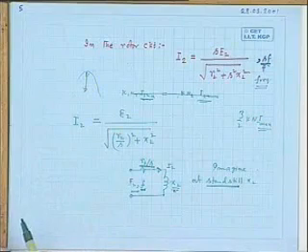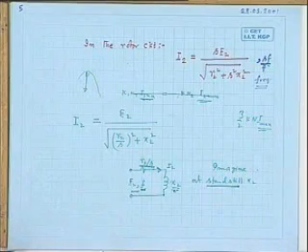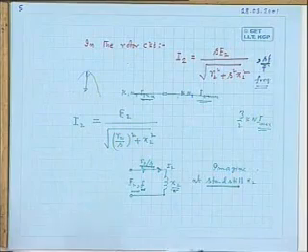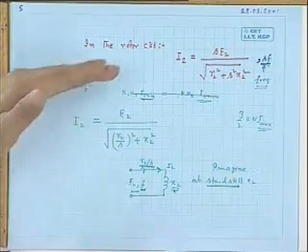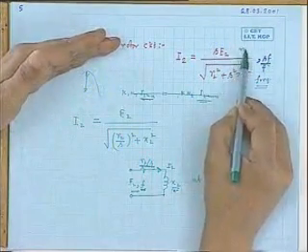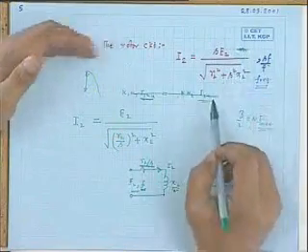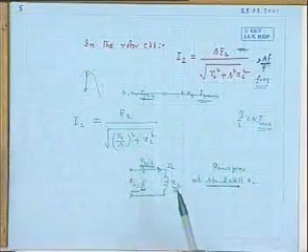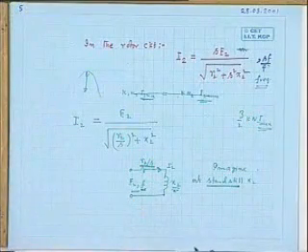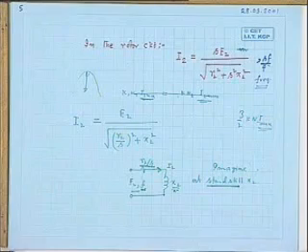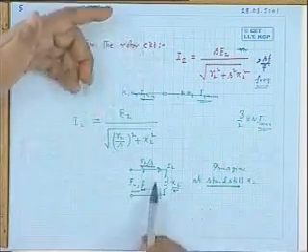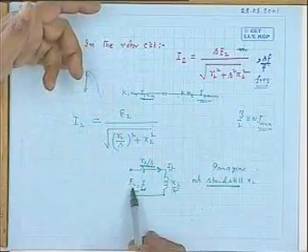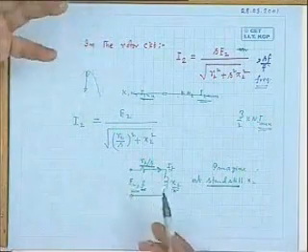Now the question is, the stator will react to that and it will draw extra current. My question to you is this. In these two cases, when this machine is running with some speed NR, with a slip S, can the stator distinguish between these two cases while reacting to it? It cannot, because the magnitude of the current is I2, although the frequency is F.